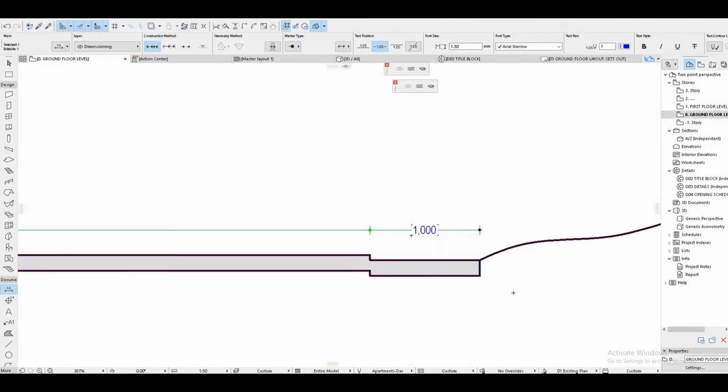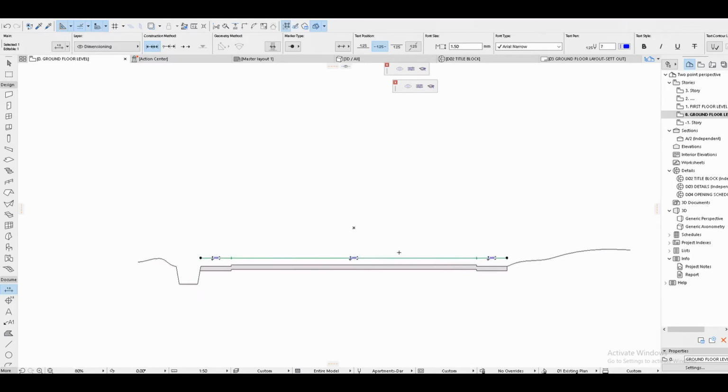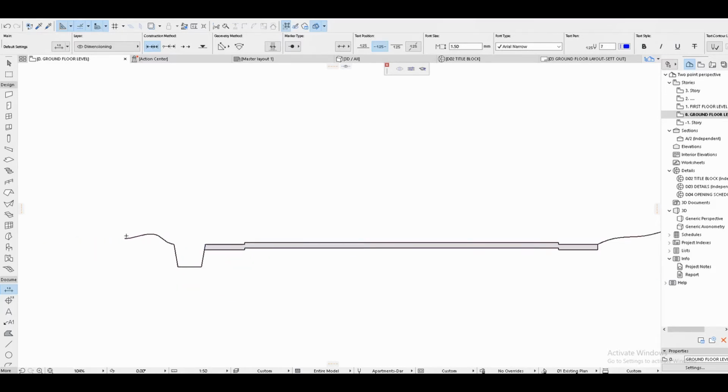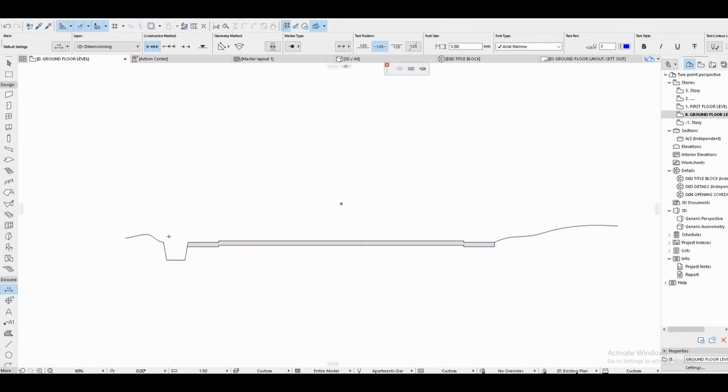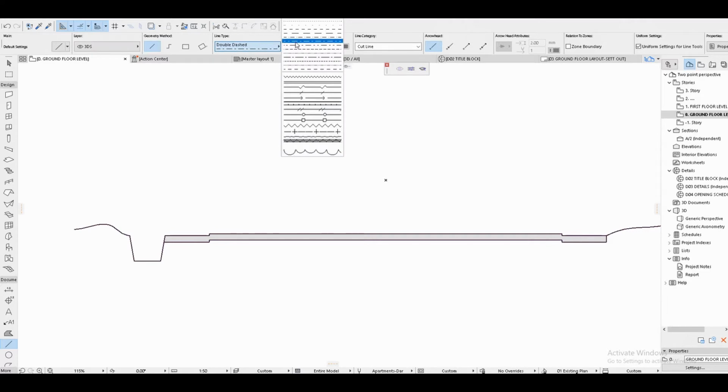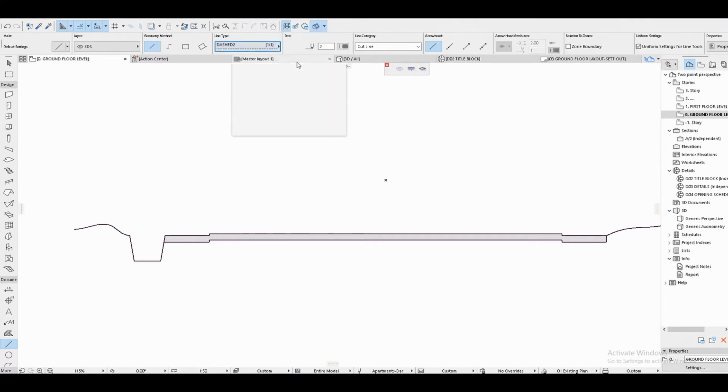I also decided to include a trench or a drain on one side and an even ground on both sides. Now let us start. The first thing we start with is the reference line. The reference line should be faint, maybe dotted, and should be on the upper side of the object you want to project.